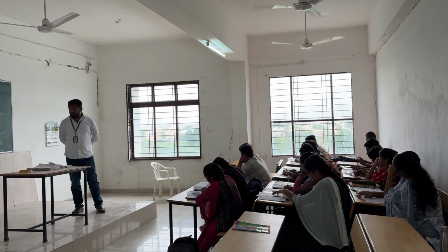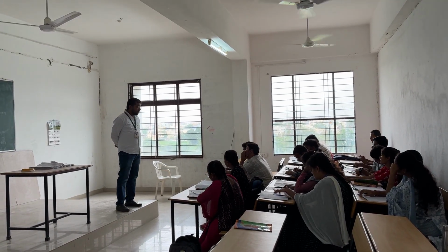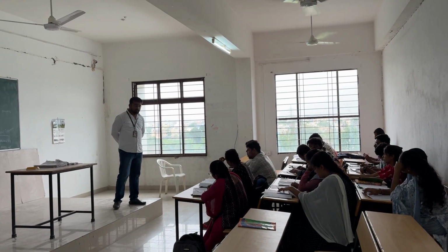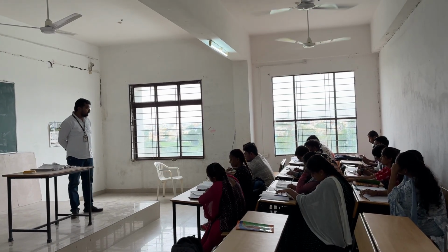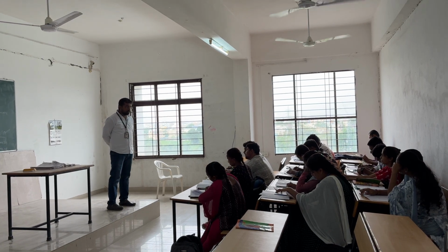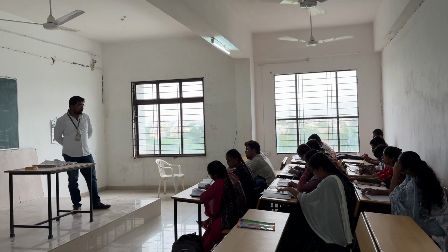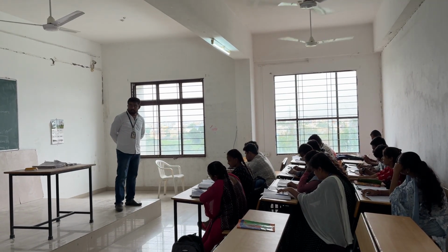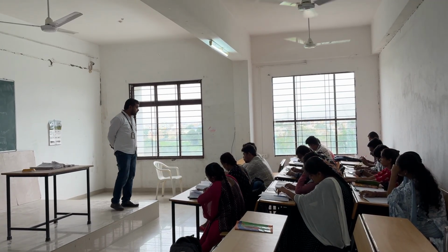Area, depth and location of treatment required. As in the foundation engineering subject, it depends upon the type of soil, whether it is red soil or clay soil. Suppose it is red soil, we need to go for a shallow foundation. Whenever it is cohesive soil, like clay soil or black cotton soil, we need to go for a deep foundation, or wide foundation. Depending upon the type of strata developed, we need to decide the depth. Whenever the soil is weak, we need to go for more depth. Whenever the soil is strong, we will go for less depth.